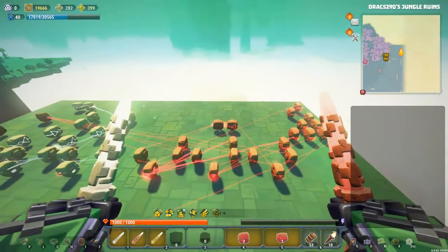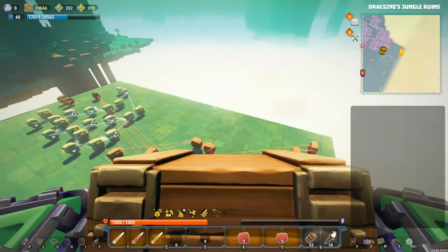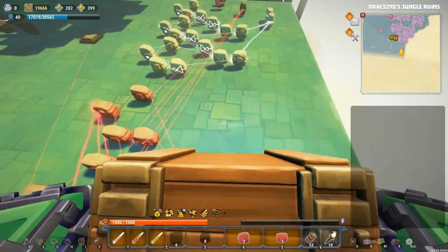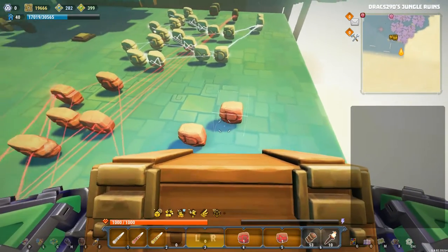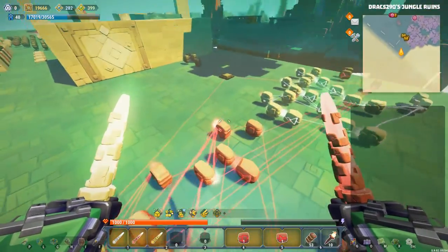So now we want to finalize this little piece of the circuit by doing the all-on protection. Now this one is actually easier than the last one. This one had a lot more gates in it. So we're going to place our all-on protection just down here. What we want to do is stagger 2 AND gates like this, because these are just going to be used to link all of the latches together.